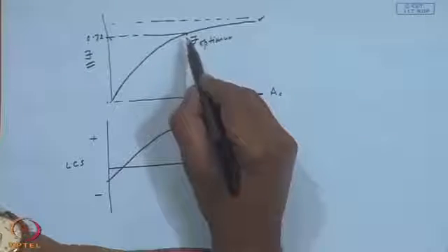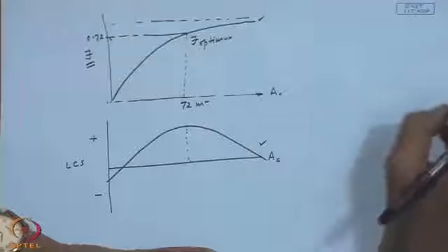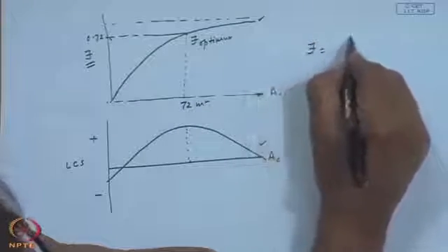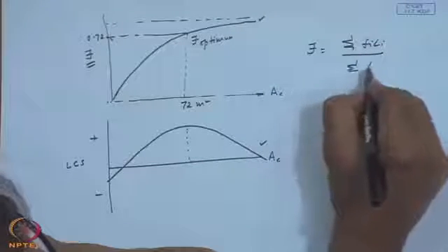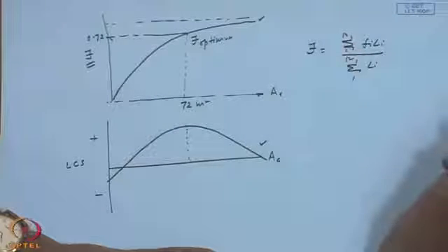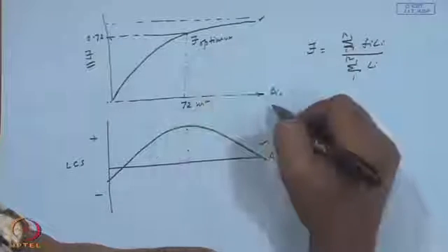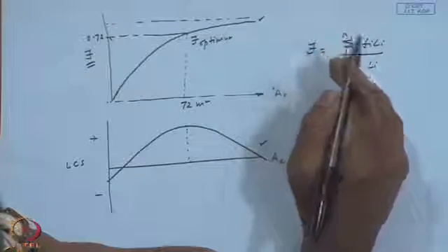is the best thing, because till now when we made the f-chart calculations, though we made it only for one month, one can in principle make it for all the 12 months and find out capital F is sigma Fi Li over sigma Li, 1 to 12, and obtain this curve, and we have already established sufficiently strongly that this F versus AC curve will be nonlinear with the second derivative being negative.